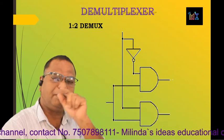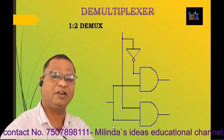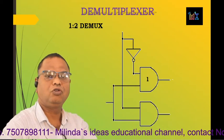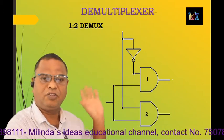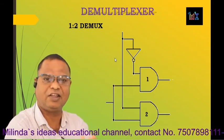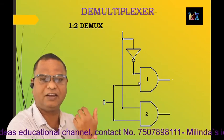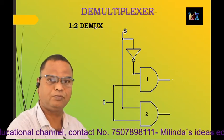The control input is applied to the AND gates through NOT gates, while the data input or input signal is applied to the AND gates, and the outputs of the AND gates are considered as outputs of the demultiplexer. Now the circuit diagram of 1:2 demux is going to be displayed on your screen. From this circuit diagram, it is clear that in case of 1:2 demux, two AND gates are used. The input signal, that is I, is connected to both the AND gates, so that I is common to both the AND gates. The second input for each AND gate is a select input or control input.